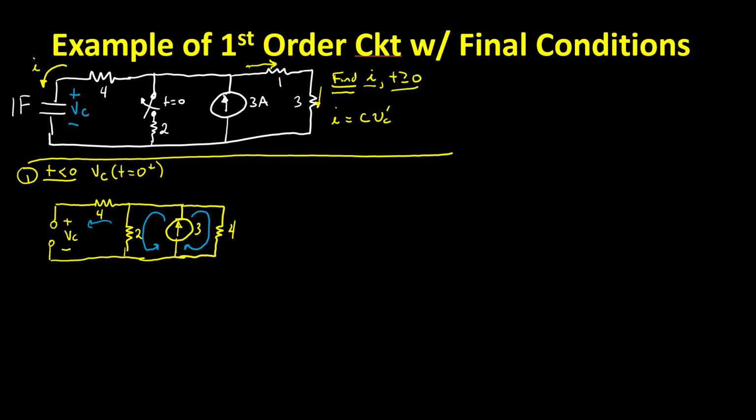Just a plain old 9-volt battery held in your hand has a voltage across the terminals, but no current. What it means is that since there's no current flowing through that 4 ohm resistor, I know right now that the voltage across that 4 ohm resistor is 0 volts. So VC therefore has to be the same as that voltage. And that simplifies my circuit a lot.